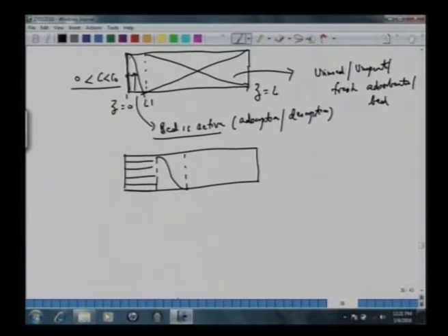So look at this profile, which was like this at the inlet, now it has moved like this, and this is a region where the wave has not reached or the bed is still fresh. So now let's mark this point, let's call it L2 prime and L2 here. So this is the region where we are saying that the bed is saturated.